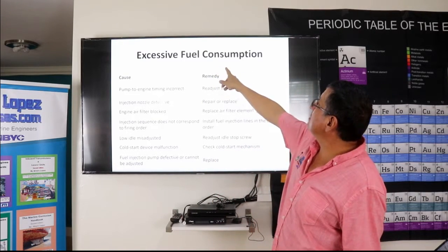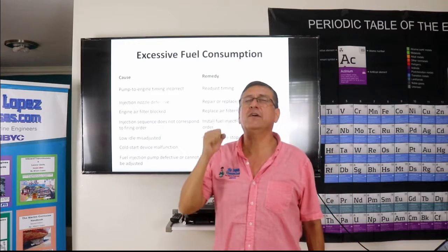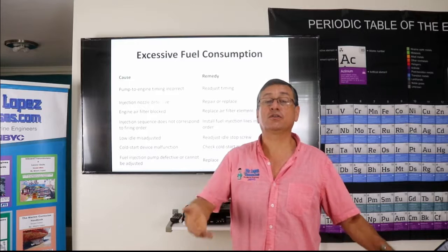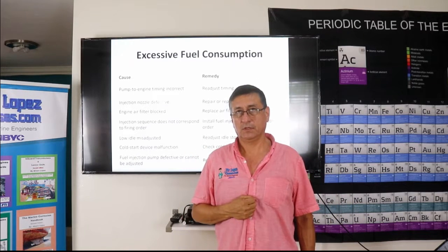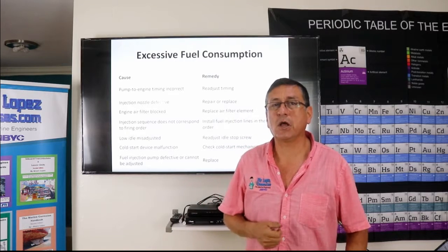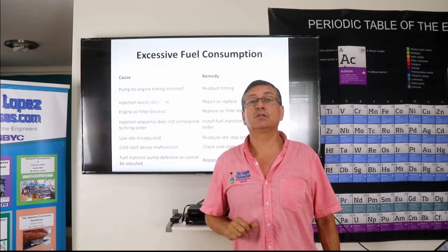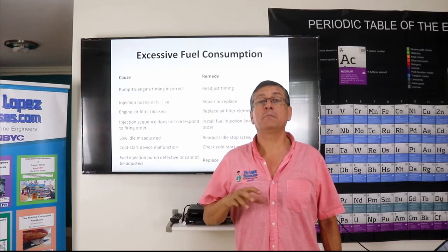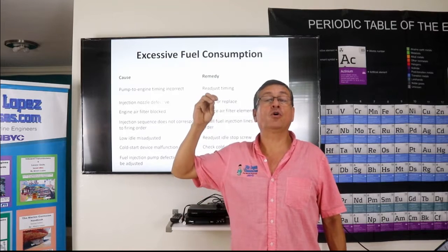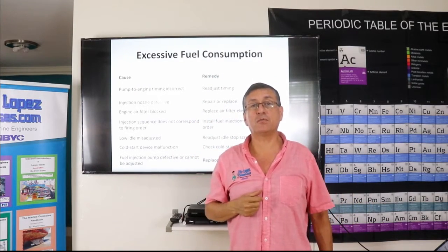Other is excessive fuel consumption. Okay, before we read the table, excessive fuel consumption. What is the most common cause for that situation? Yes, the air filter is clogged. Or a couple of injectors open too much, or stay open all the time because the injectors are broken.